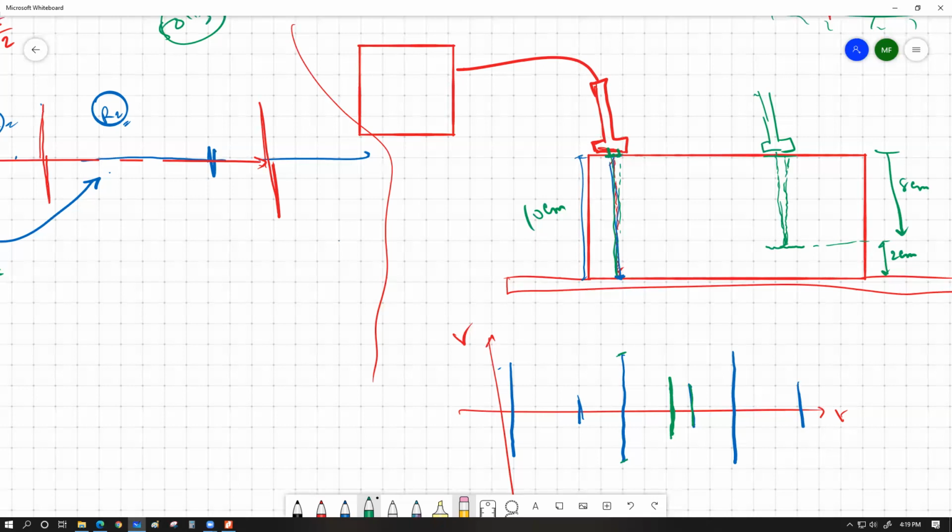And obviously you should understand that whenever we have the reflection over here, this sudden appearance of a new pulse on our screen actually shows that this metal might have, not might, it does have some problem or cracks within this metal piece somewhere at a certain length.